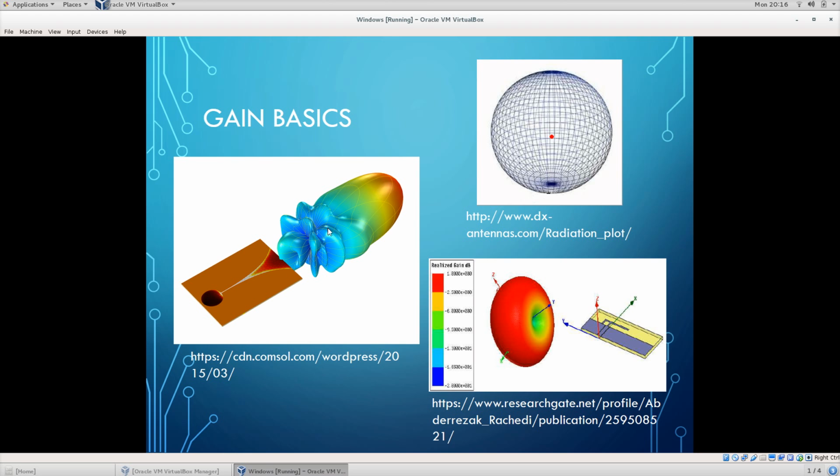So like in this case, this is another 3D pattern. You'll notice the back lobes here are blue, which means that there's less energy going this direction, and the heat map shows red up here, which means it's putting a fair amount more gain up here, but it has kind of an interesting look to it. However, again, this is in dB. This is actually probably a fairly good directional antenna.